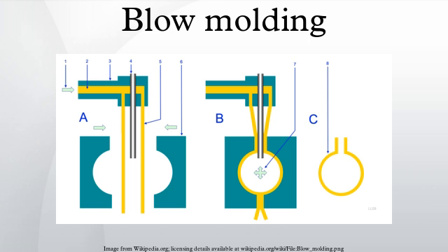Advantages of blow molding include low tool and die cost, fast production rates, and the ability to mold complex parts. Handles can be incorporated in the design. Disadvantages of blow molding include being limited to hollow parts, and low strength. To increase barrier properties, multi-layer parisons of different materials are used, thus not recyclable. To make wide-neck jars, spin trimming is necessary.